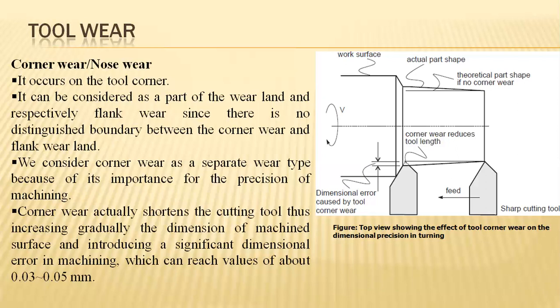But if the feed rates or depth of cut are increased, that leads to the formation of this corner wear or nose wear in that particular situation. A rough surface finish will be achieved, leading to a high MRR process.